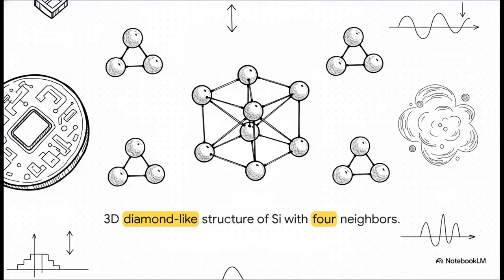Let's focus in on the actual raw materials that possess this perfect, intermediate Goldilocks gap. The most famous ones, of course, being silicon and germanium. In this incredibly pure or intrinsic state, every single silicon atom shares its 4 outer valence electrons with 4 neighboring atoms. This completely locks them into a very strong, highly stable, 3-dimensional diamond-like covalent lattice. Essentially, every single electron has a partner.